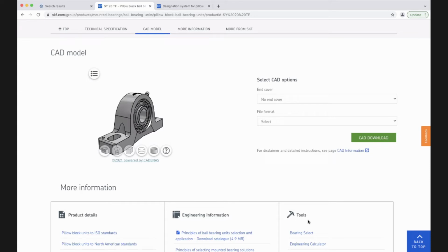You could, in theory, put the freedom to slide on the joint between the housing and the chassis. I think, yeah, I mean, you're right from the point of view of looking at the theory. I think in practice, you'd probably find that was more difficult and you'd have to worry about exactly how it would work in practice because you've got these two bolts. And if you were leaving them loose so that it could move, then it could twist sideways and rattle around. So I think in practice, the best solution is probably to slide on the inside, but that's a good thought.